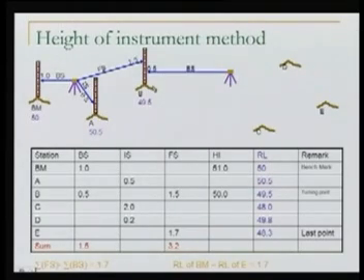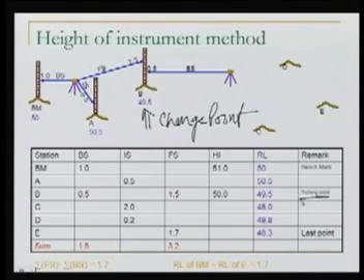Okay, we have taken a back sight here. One more thing now at this point which is important. This point B we say as turning point or change point. As I have also written here, turning point. This is also called change point because this is where we are changing our level. And at turning point or change point, the sight which is taken is the foresight.